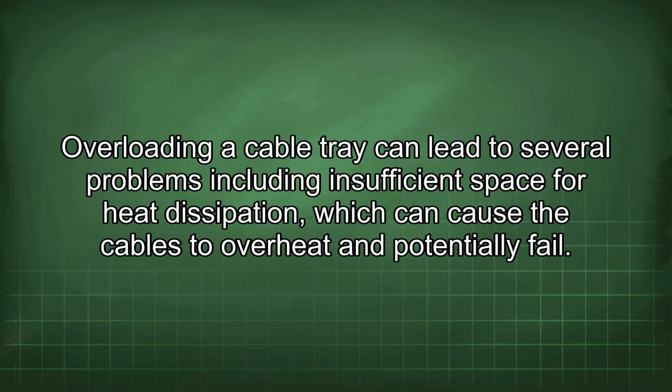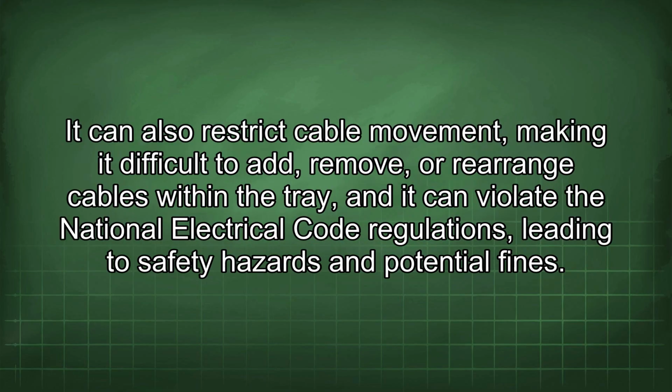Overloading a cable tray can lead to several problems, including insufficient space for heat dissipation, which can cause the cables to overheat and potentially fail. It can also restrict cable movement, making it difficult to add, remove, or rearrange cables within the tray, and it can violate the National Electrical Code regulations, leading to safety hazards and potential fines.